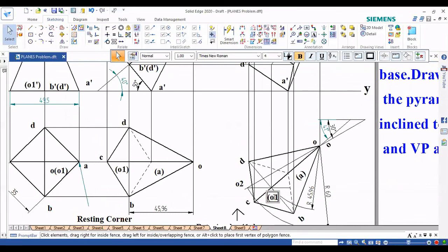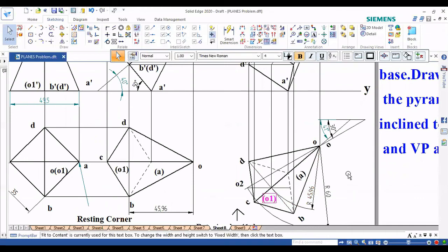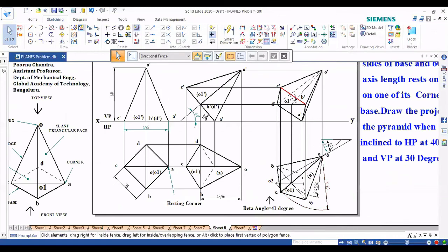So O1, then you can project this up. Okay. So project up and join that. So for construction of this, once you get the O1 line, project it, draw a perpendicular line for O1. You can mark D and B with compass, measuring this length. Then project downwards, measure O1C and cut it. Then construct this picture.